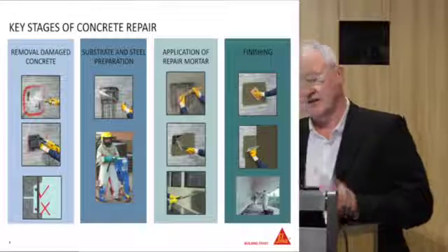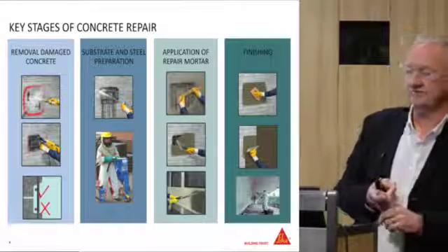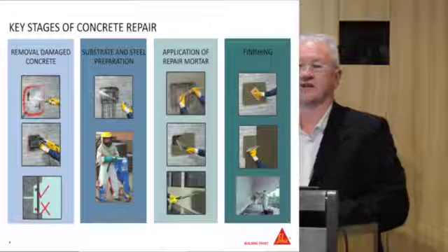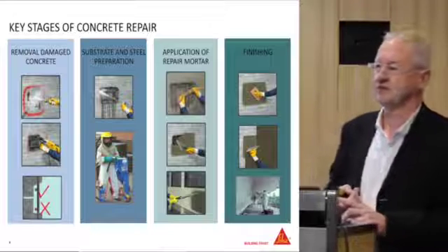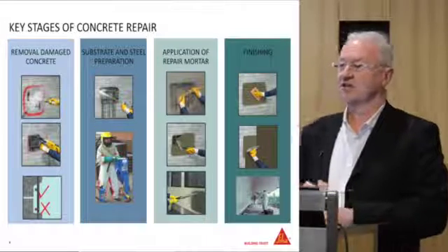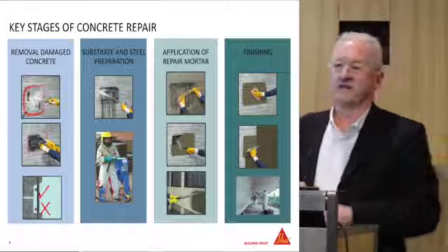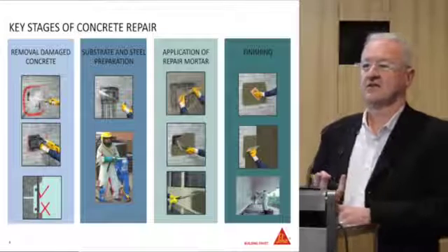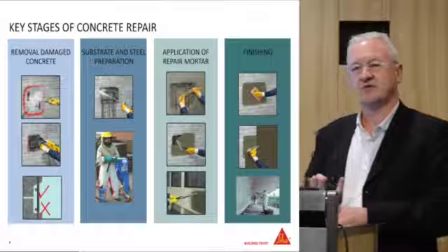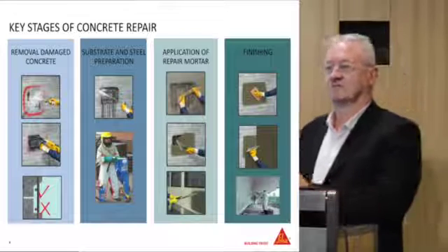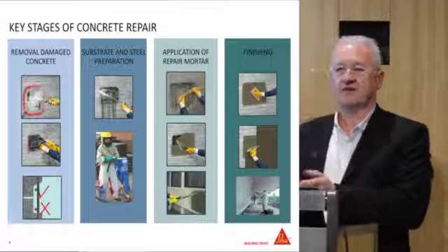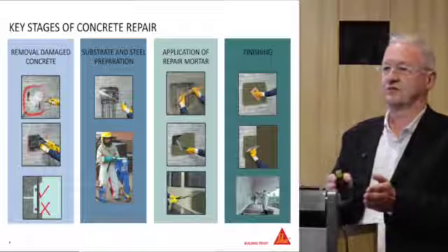Part 3, there's R1, which is sort of low strength concrete, up to about 10 to 15 newtons per millimetre squared. There's an R2, which takes you up to about 20, and then you have an R3, which is up to, I think, about 30 newtons per millimetre squared. They're classed as non-structural repair mortars. And then you've got R4, which is the structural repair mortar.